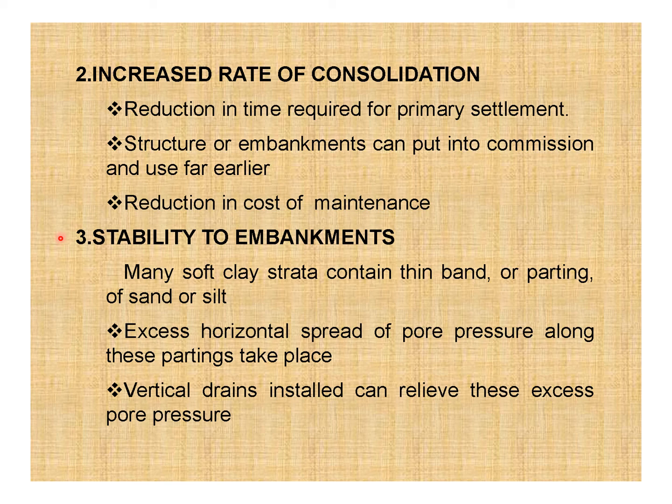And the third aspect is the stability of embankments. Many soft clay strata contain thin bands or partings of sand or silt. Excess horizontal spread of pore pressure along these partings takes place. Vertical drains installed can relieve these excess pore pressures.